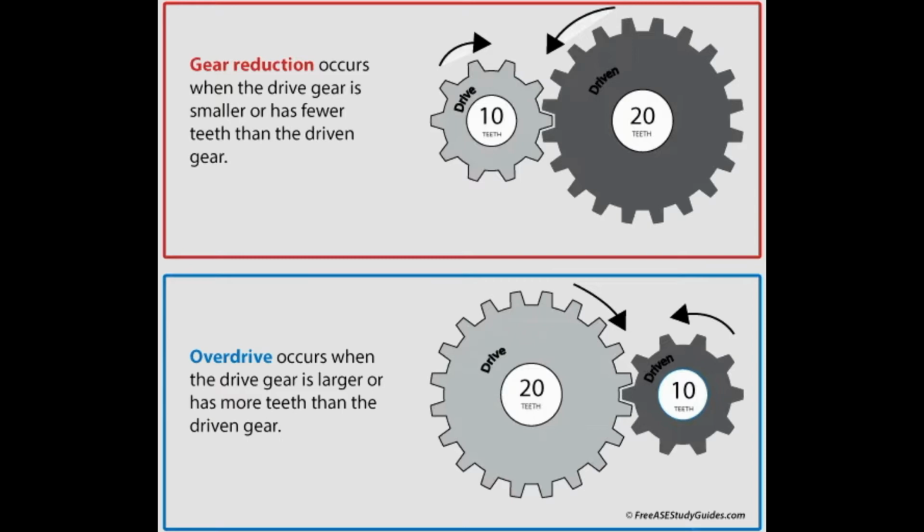Why do we need gear ratio? Since we know that the combustion of air-fuel causes the piston movement, which in turn rotates the crankshaft of the internal combustion engine, which is the engine's final output, if we use this output directly as the final output for the wheel rotation, then the wheels of the vehicle would rotate at the same torque and speed provided by the crankshaft, which is not enough to fulfill the challenges given by the road conditions.